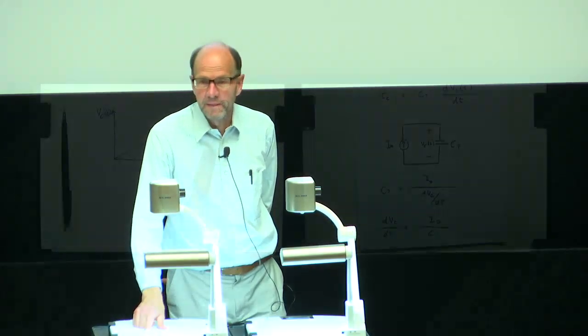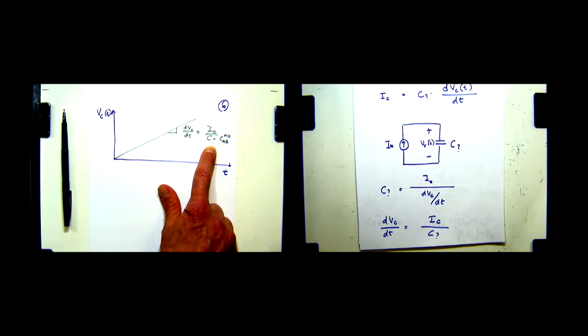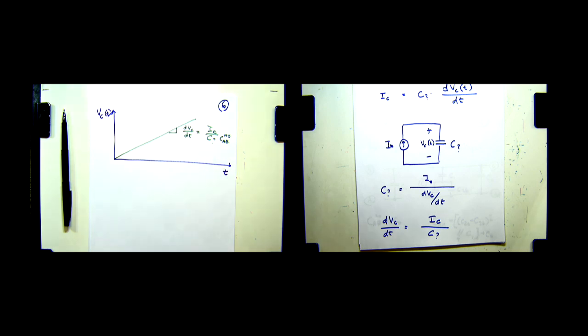Well, I0, does it change? No, that's our test current source that we somehow cooked up in the lab. It doesn't know that the finger suddenly is present. Well, then there is another choice. The capacitance C question mark. That one is now larger or smaller? It's going to be larger.